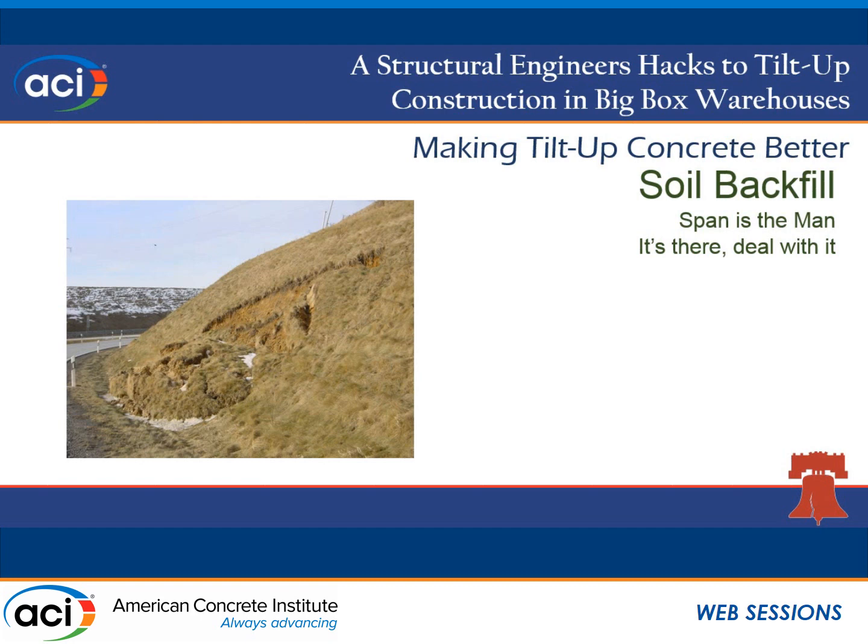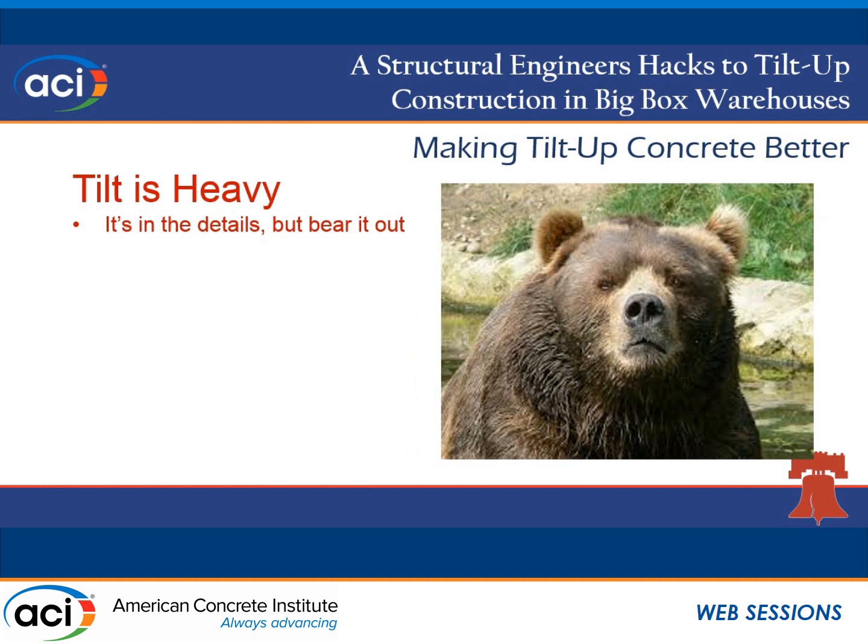The other thing is, if you do decide to try to span those panels from the footing to the roof, make sure you've accounted for it. Yeah, it's in the bottom 5 feet of your panel, but if you're not tying back to the slab and trying to make it span, which isn't my recommendation, but if you're doing it, make sure you've accounted for it in the same way that you would for all the other loads, okay? It's a 1.6 factor in LRFD design. It can really impact your deflection.